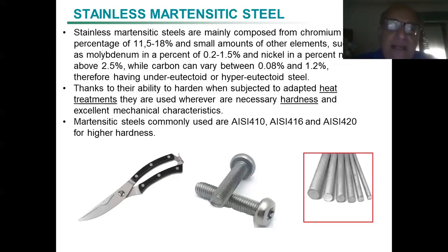to add other elements. Usually you have always, likely not in large quantities, molybdenum, and you have also a larger amount of carbon. Carbon in this case is not very close to the lower limit, but you have carbon around 0.9%, so around the eutectoid.